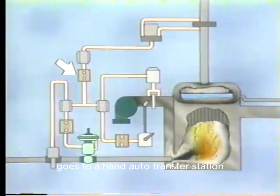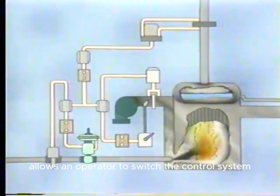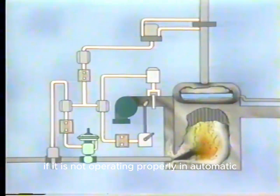The output signal from the controller goes to a hand auto transfer station. As you know, a hand auto transfer station allows an operator to switch the control system from automatic to manual. This permits him to control the process manually if it is not operating properly in automatic.